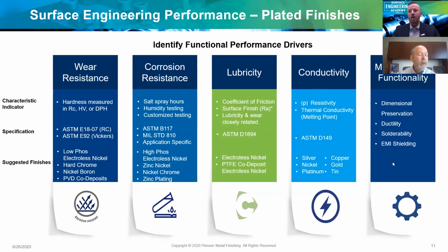But overall, there's other considerations such as preserving the dimensions of the part. As you mentioned, there's the masking, but again, Electroless nickel does a great job here in that it's going to provide a very uniform finish. And then the ductility of the coating, if the part's going to be flexed, if there's any inflection, it's important to have a coating that can stand up to that. It can be stressed and not break.